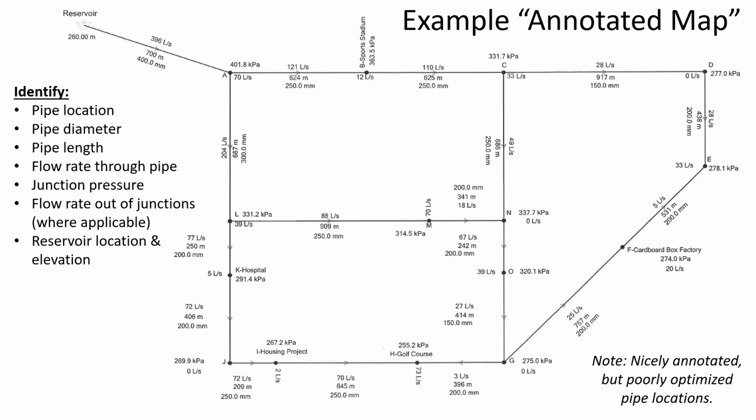The overnight condition when nobody's using any water, and then the design condition, which may only roll around occasionally, that there would be both a fire and a stadium event, and they're watering at the golf course and the residential areas at peak demand. So all those things are assuming they happen simultaneously. We want to have a network that's robust enough to maintain the minimum pressure of 240 kilopascals at every location in the network when that occurs. So, therefore, 2 maps.